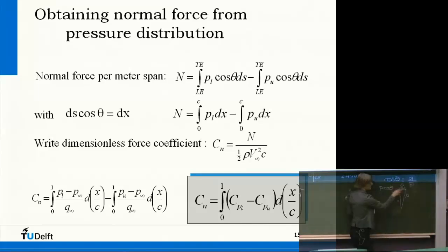Right, we're projecting pressure on the normal direction. Then this is the long side of the triangle. Then if this is theta, cosine theta is equal to the shorter side over the long one, so A over P. So then we find that A is equal to P cosine theta. Yeah, you agree? Okay, good.